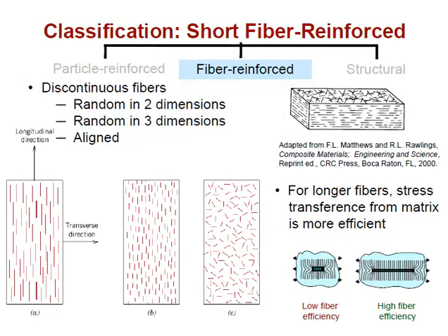You have stress being applied right to left, horizontal on the schematic. And in the case of the short fiber, which is said to have low fiber efficiency, those isostress lines that you see in the matrix that are running vertically in the slide indicate that the matrix is carrying most of the load at the ends of the fibers because it's the only thing there.